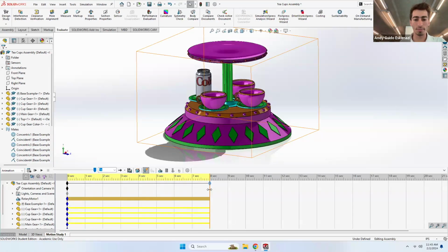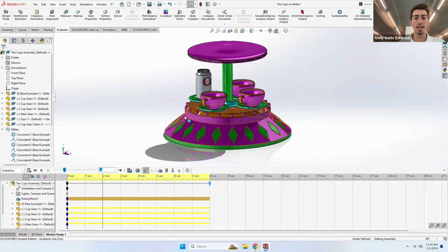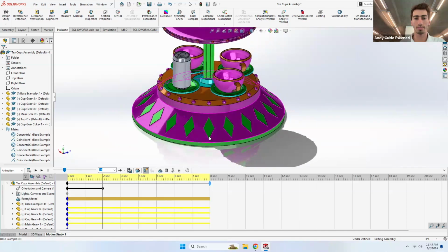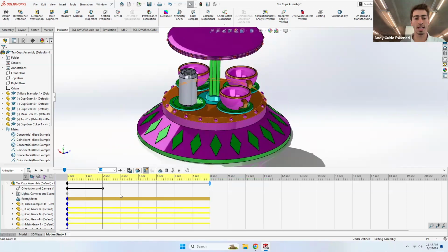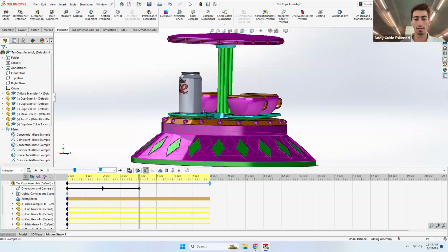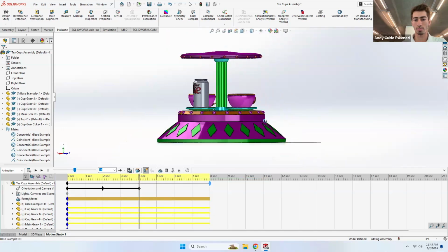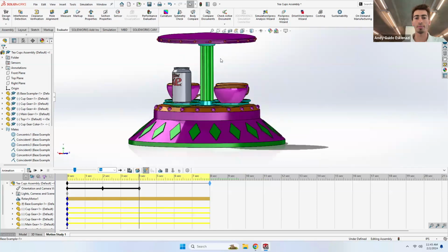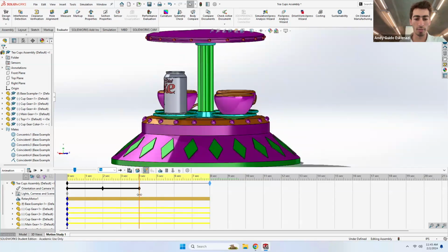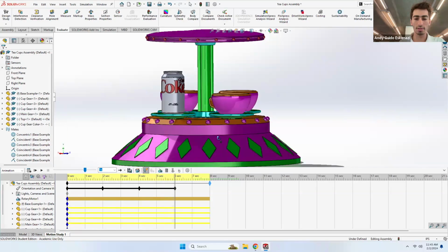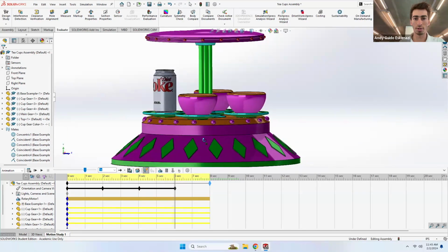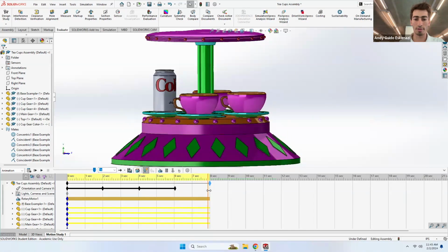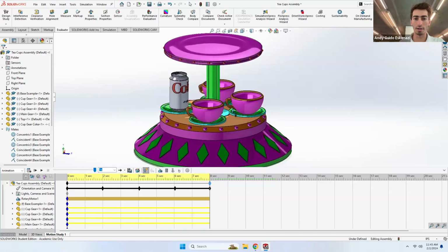And then there's another thing, which is if I click here on where it says orientation, I can click on here where it says disable key. And as long as that little key is pressed on, then I can do something like this. And you see that now it creates a different key. So now if I were to do this, it stores the position at which I'm going. Then I can do maybe for the next 6 seconds, what if you rotate a little bit like that? And for the last 8 seconds, let's return to this configuration.